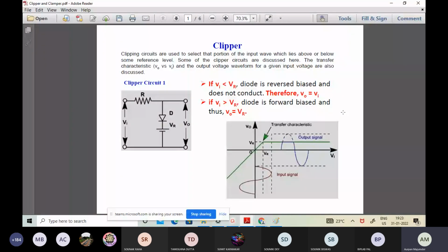But the point is, in that segment of operation for the rectifier, we have a level of discharging going on, but the discharge level is very low. When we're talking about a clamping circuit specifically, it has a very similar idea. The discharging level is too low, which indicates the value of R into C should be excessively high. If you can maintain that kind of circuit, then we can generate clamping circuits. So we'll get to the corresponding circuit.